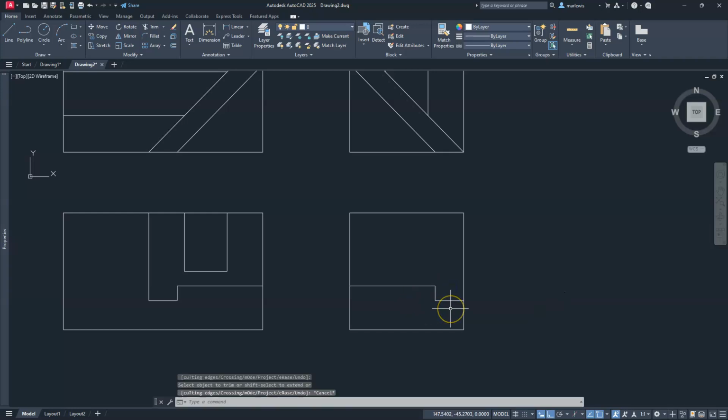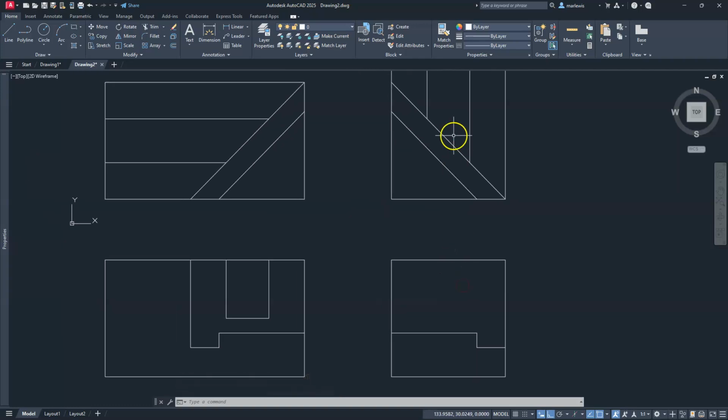Okay. Next, I'll go ahead and put this kind of U shape here at the top of it. Remember that we do have the lines up here at the top, and we do have the lines over here at the side. So if I go to the line command, all I have to do is touch that intersection, come down to where it intersects here, do a left click, come down, go and touch that endpoint, come over this direction, place it here.